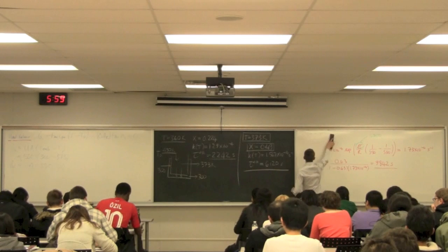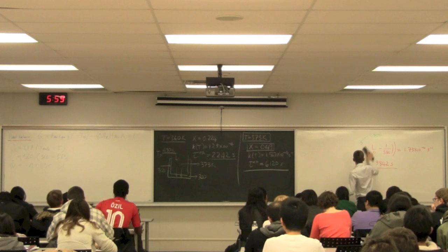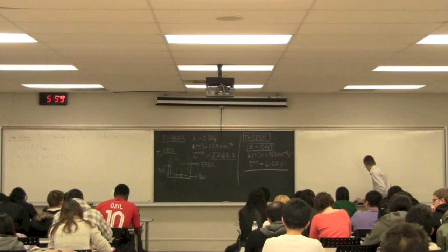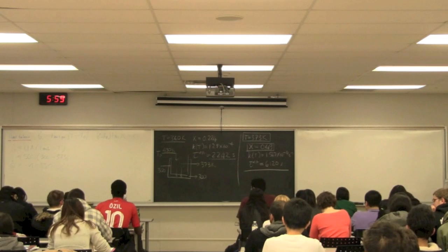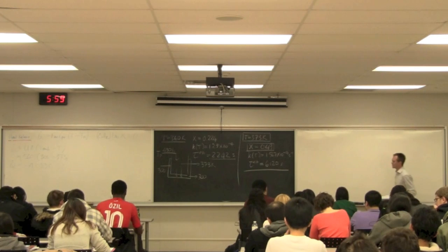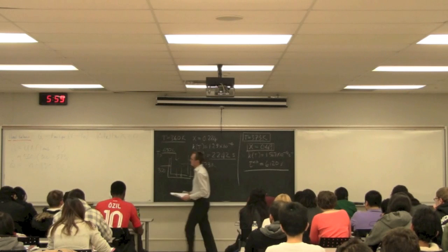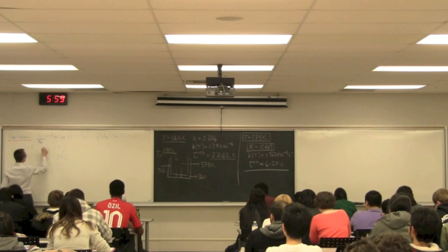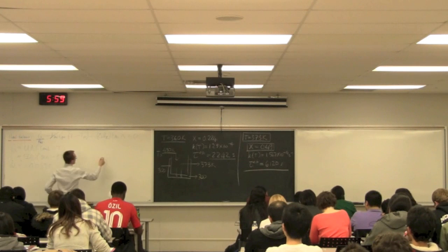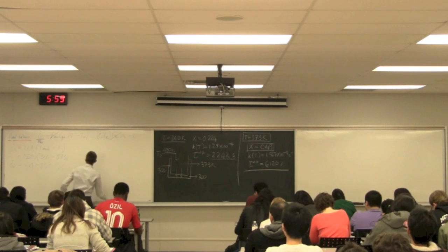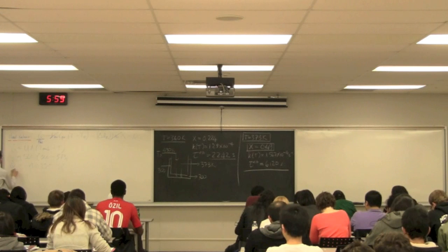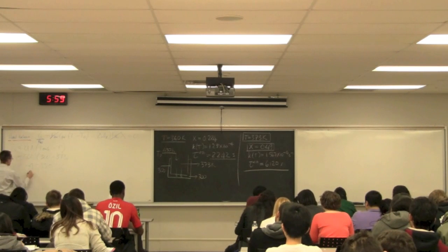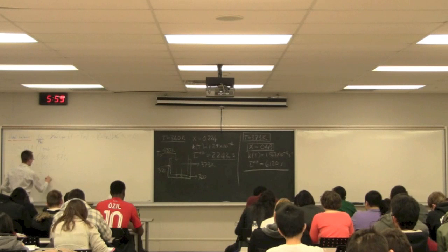Let's take a look at that last term, the heat of reaction term. And what I'll just do before we get to that point is to just do what's standard in the textbook, is we actually divide this equation out by FA naught. So we generally represent this divide by FA naught. Take that FA naught out, take that FA naught out. Okay, so let's report actually Q dot divided by FA naught here. So now let's divide by 1.3 moles per second.